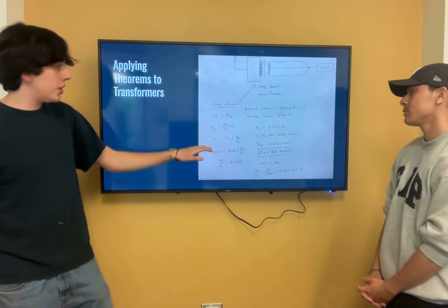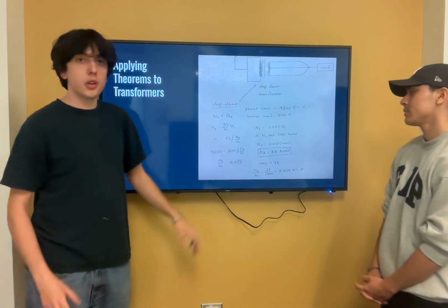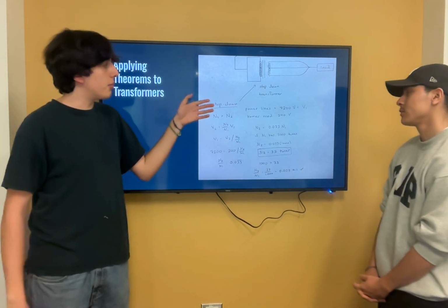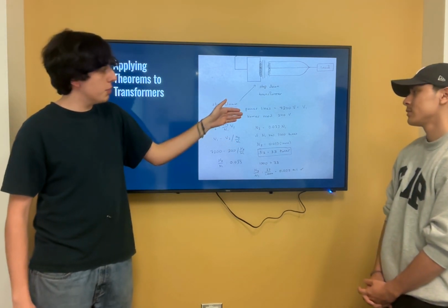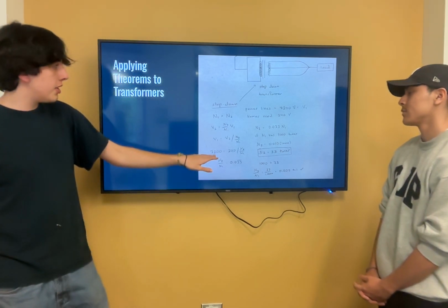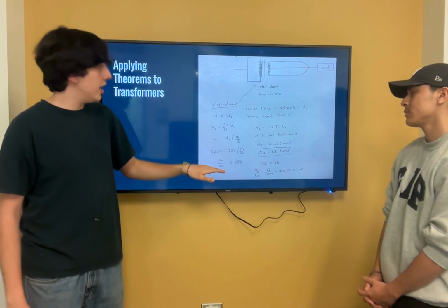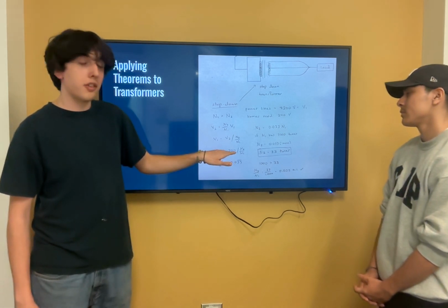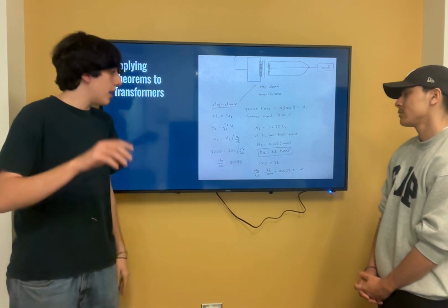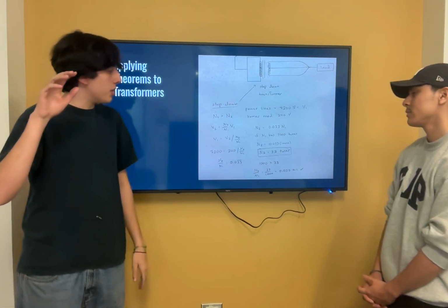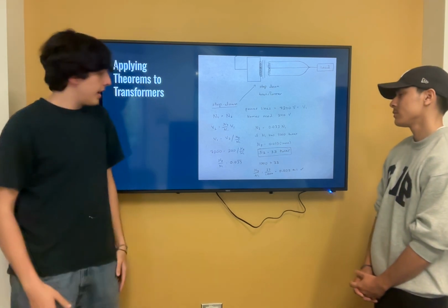We rearranged this equation just to look at what the coil ratio would be based on the regular voltages in power lines and homes. We set it up so that the input voltage of 7,200 is equal to the output voltage of 240 volts over the number of coils output over input.